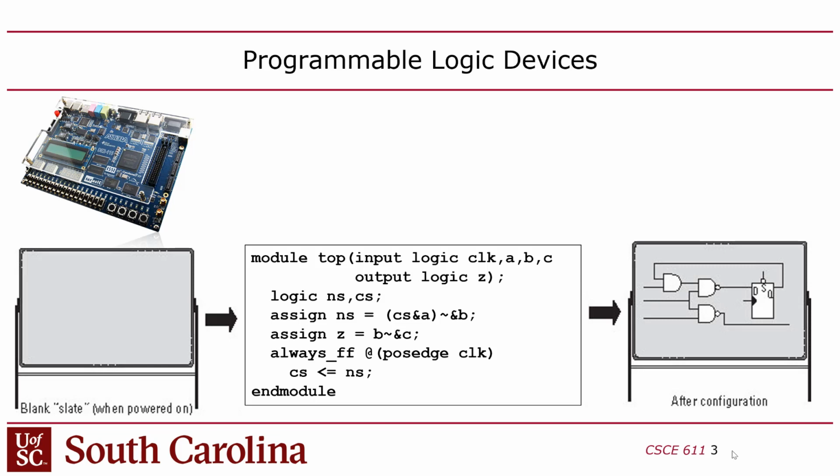And then the design is stored in volatile memory. So if you power the board off, you lose the design, although typically these boards, and this one included, have a non-volatile memory that's off chip that automatically gets loaded in when you power it on. So when you power these things on, it comes up into a default configuration that's actually someone's design. It was loaded from the SRAM or the flash RAM on there.